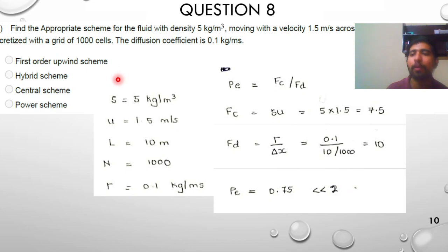So always remember, it's not only about your flow, magnitude or direction. You have to always check with the grid also. This might seem a bit counterintuitive, but it is the flow of information that also matters, and that is determined by your grid spacing. You will particularly learn this in time marching schemes, wherein we will see CFL conditions later on. There also the grid spacing will matter to a very large extent. So you have to keep this in mind.